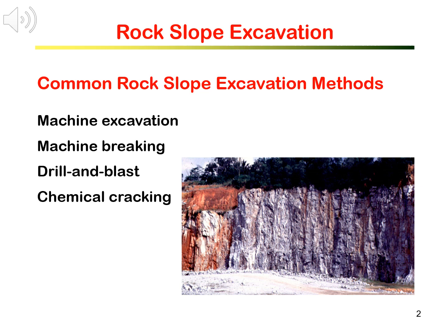To cut or to excavate rock slopes, common rock slope excavation methods used in modern days are machine excavation, machine impact breaking, drill and blast using explosives, and the cracking by chemical to expand and break the rocks.